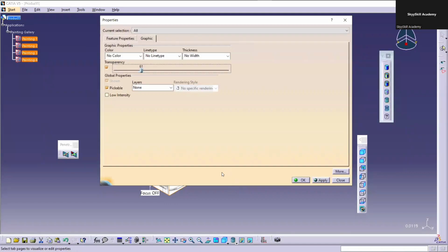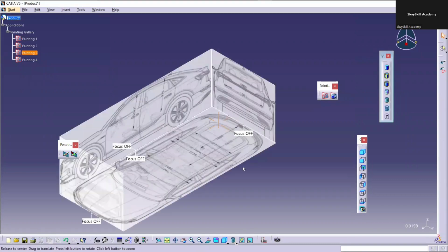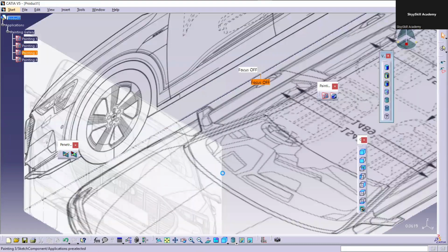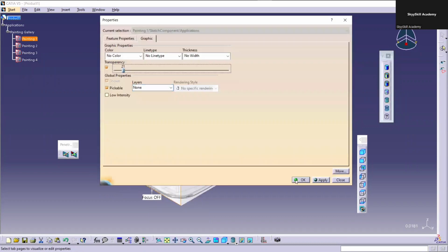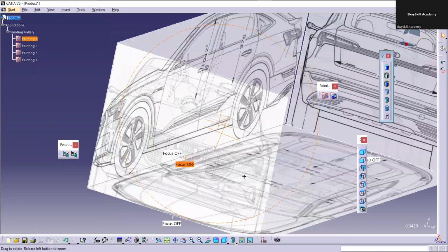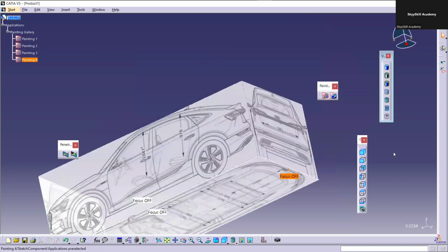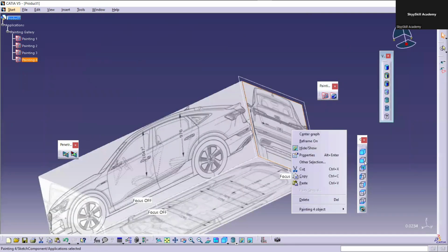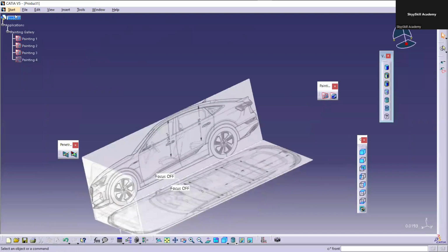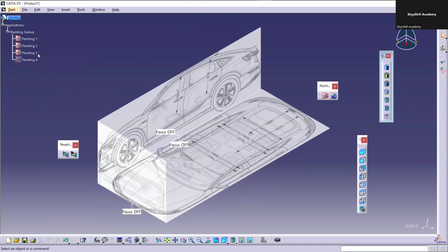So now let me just start adding my part files. Let me select this, and I think it has more transparency. Let me hide this view, this area. I don't need this for now. Okay, so it's done. Now what I will do is insert my part. So I'll go for product, then insert new part. So, new part to this product.